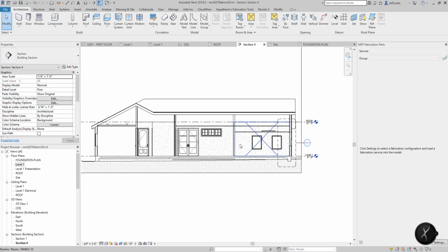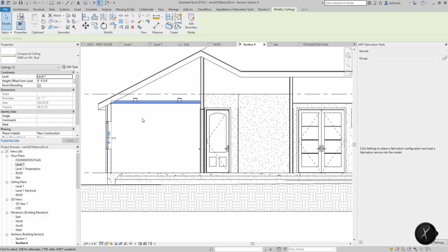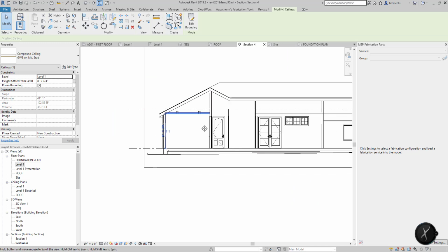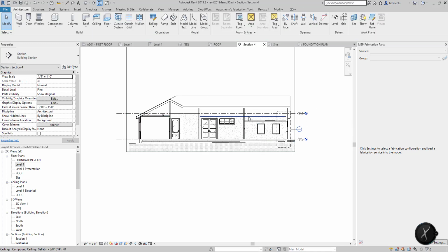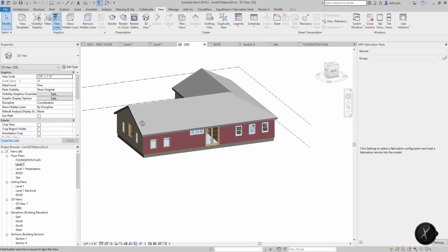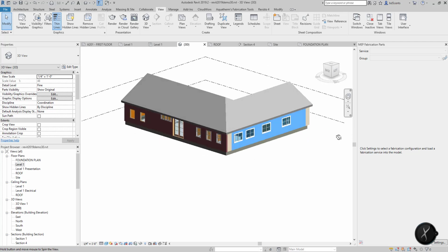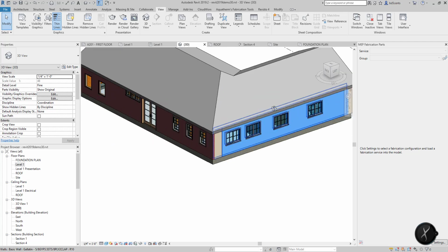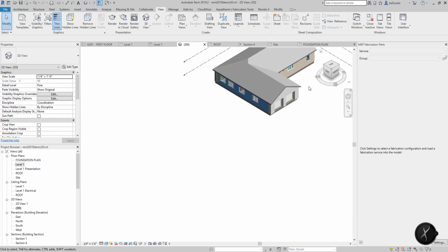Now we've used the sketch option and we've set it approximately at the right height. That's 8'9 3/4". Once everything's in the right spot, we can then send this off to the truss manufacturer to build it in relationship to our ceilings and roof. Now we want to move into wall sweeps, but that'll be the next lecture. So for now, we'll go to a 3D view to ensure that our roof's set up correctly. We have a brick pattern on the back that we painted on, and we'll just set this up on the top corner here.